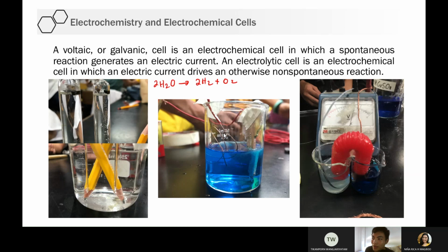When you allow electricity to pass through this setup, the copper ions will be reduced onto the metal surface. The copper ions in the solution will be reduced on the metal surface, and then we can call this metal the copper coated metal.